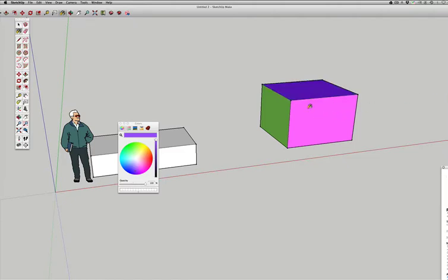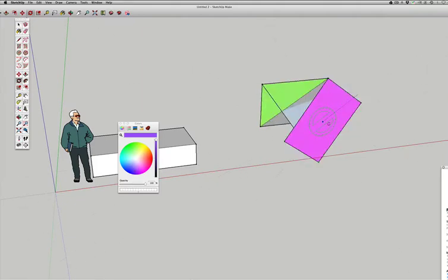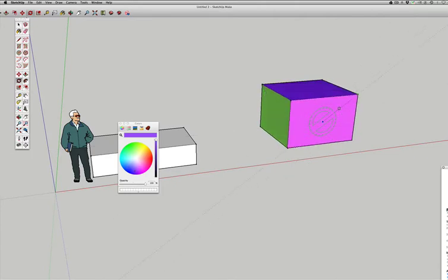So here's what you can do. You can do something called rotate. And you think, rotate should be R. It's actually Q. So I'm going to put your rotate right in that center face. I'm going to click it. I'm going to click on that end of it. Watch what happens. I can twist the face of this. How cool is that?